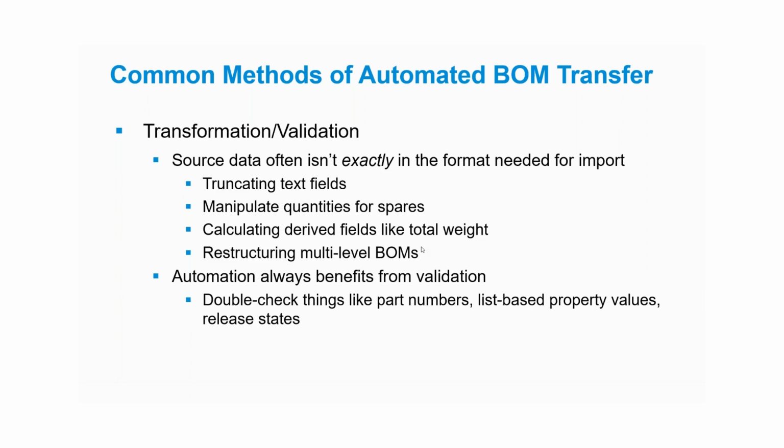We have phantom assemblies, or, say, inseparable assemblies in Inventor, and the way Inventor does things, we end up with a few extra pieces on our BOM. We want to make sure those pieces don't come out in ERP, right? Well, you can add some rules to your transformation that make sure the right parts are where they need to be.